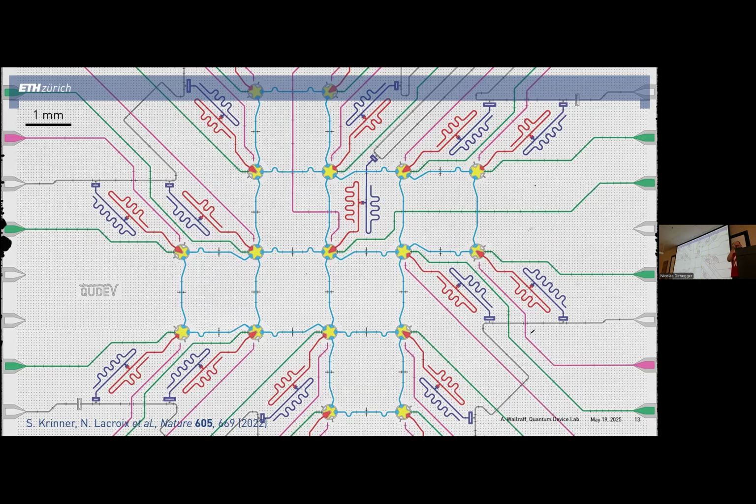The reason for this is that this device is to be used in quantum error correction, and in quantum error correction, in comparison to most general quantum algorithms, you're required to do mid-circuit measurements. So your measurements are required to be about as fast as your single or two-qubit gates, so that the measurement doesn't extend the duration of one of your error correction cycles.